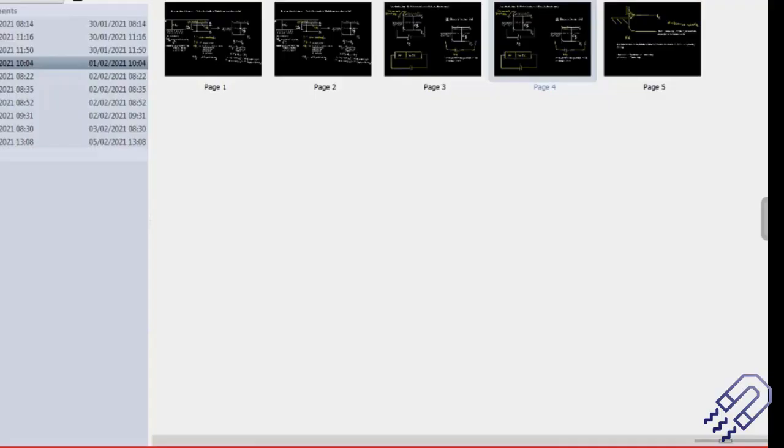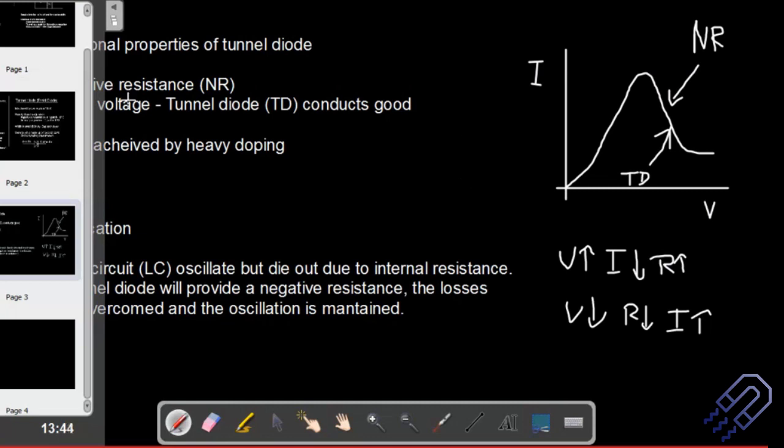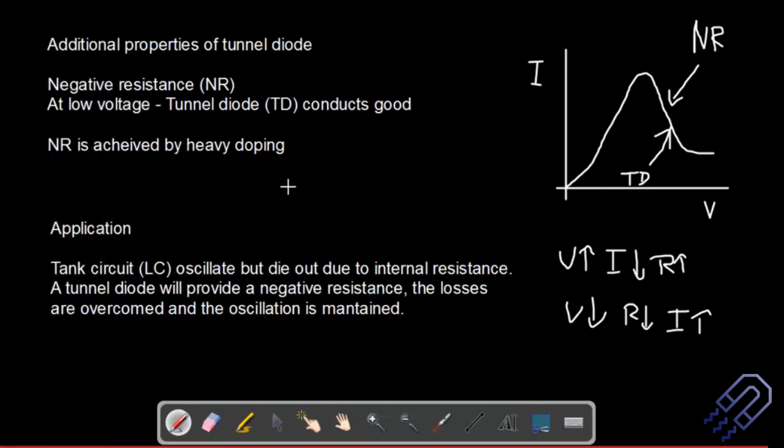So one of the fundamental questions is, if I combine any two semiconductors or any two materials, do I expect to see a tunneling effect? The answer is no, because when different semiconductors are combined, the width of the barrier will be different. For some combinations the width might be very thick, and you have to apply a very large potential so that some amount of electrons can flow from one system to the other, which affects the width of the barrier. If that happens, the electron might not tunnel at all from one end to the other. So it's all probabilistic. That's why you cannot take any two semiconductors and try to make a tunnel diode.